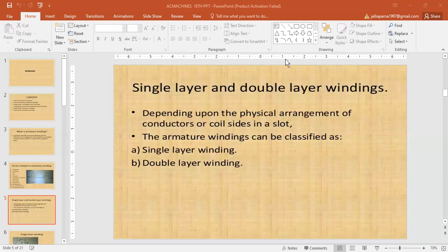Degree of re-entrancy of an armature winding. A winding is said to be singly re-entrant if, on tracing through it once, all armature winding conductors are included on returning to the starting point. It is doubly re-entrant if only half of the conductors are included in tracing through the winding once, and so on.